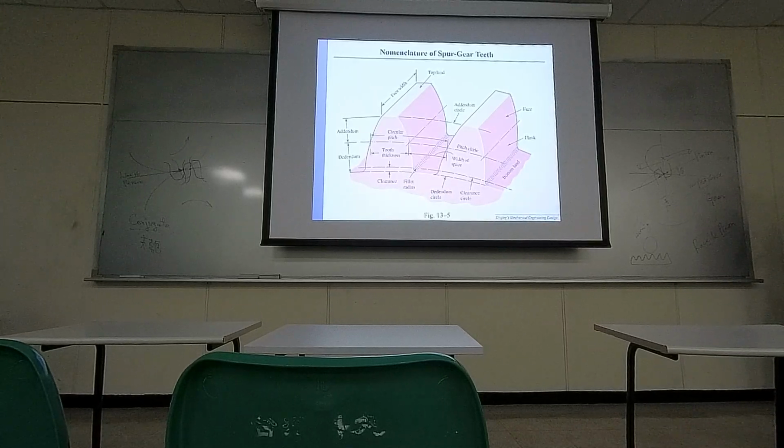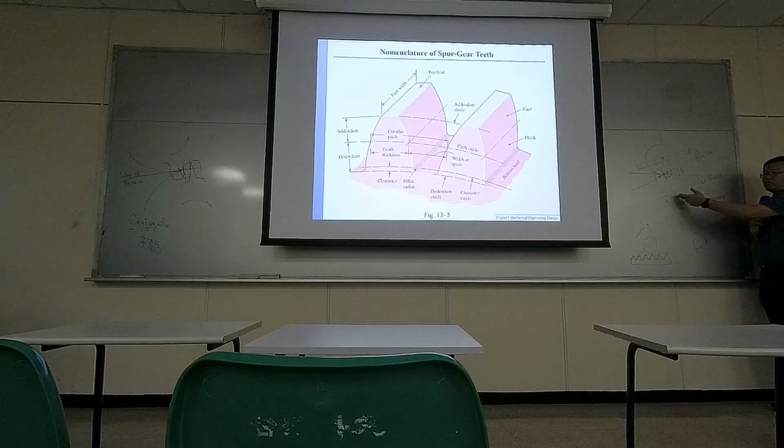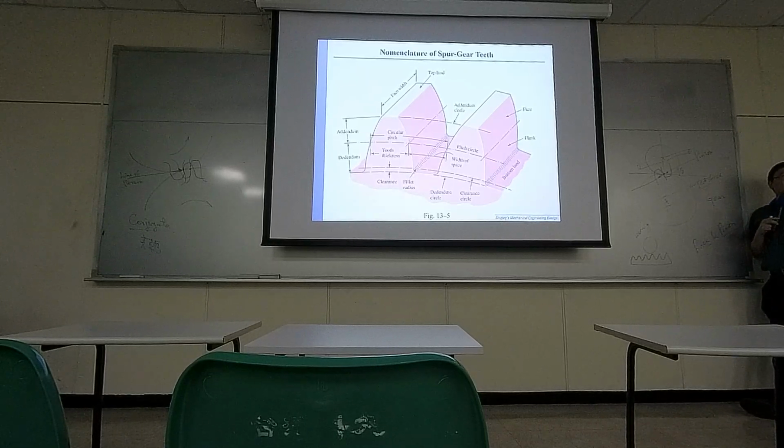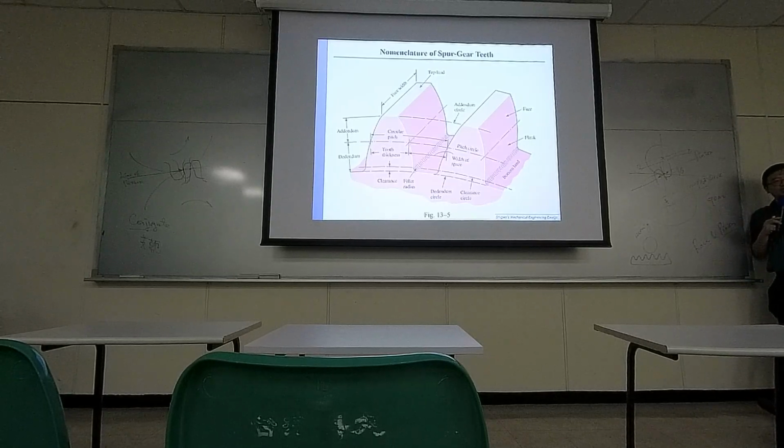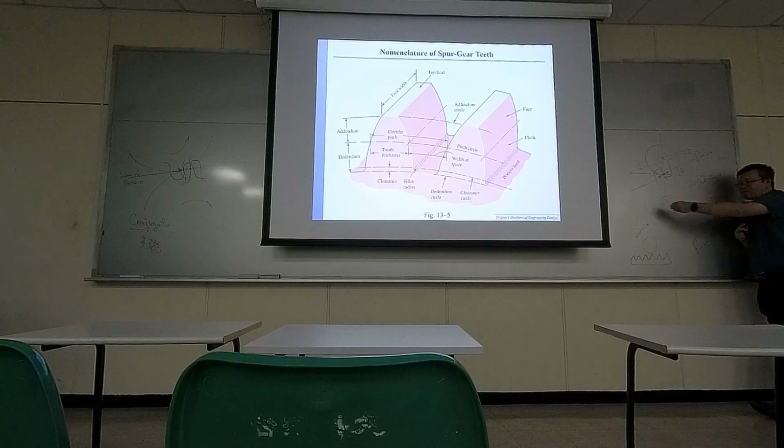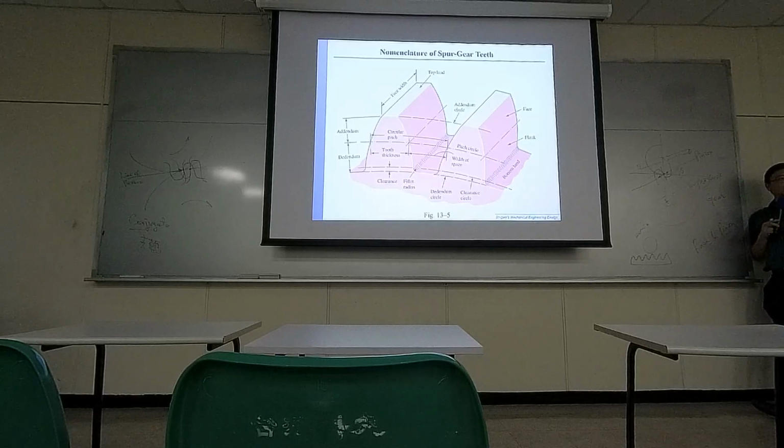Now, when we have shaft design, what do we care about? The loads inside. We care about whether there is a stress concentration, if there is any part that could have fatigue issues, safety factors. But what do we need to know first? The loading.